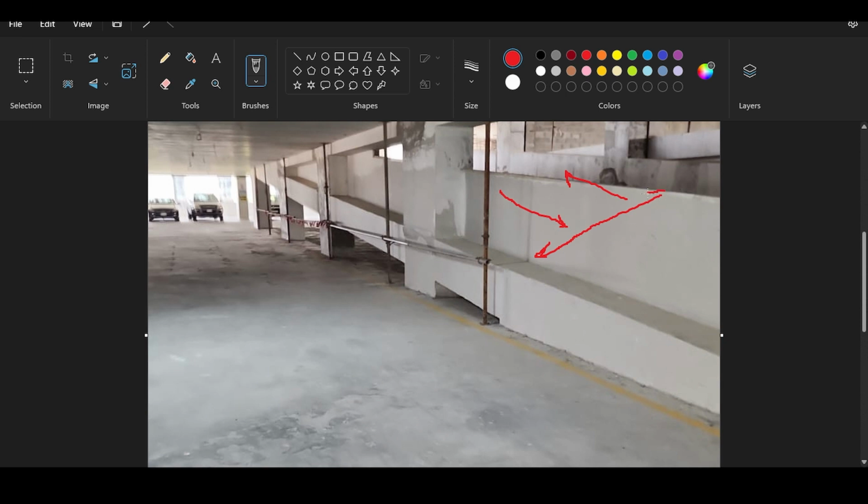Like, you could have a car going up and a car going down, and the road is wide enough to basically allow for both. Also, delta H here is 3.5. This is important for vertical clearance because you must, for each car park, provide this maximum height sign that says that the car park can only sustain 2-meter heights or something.